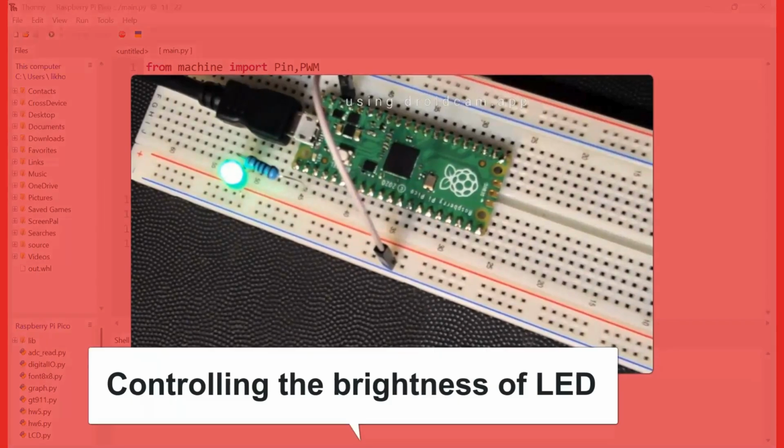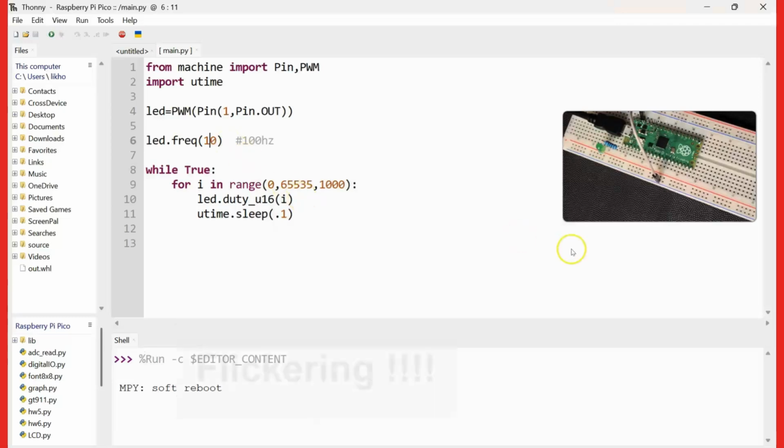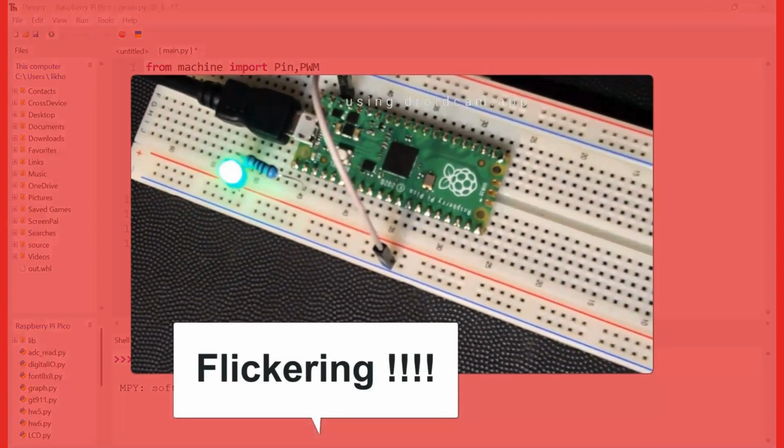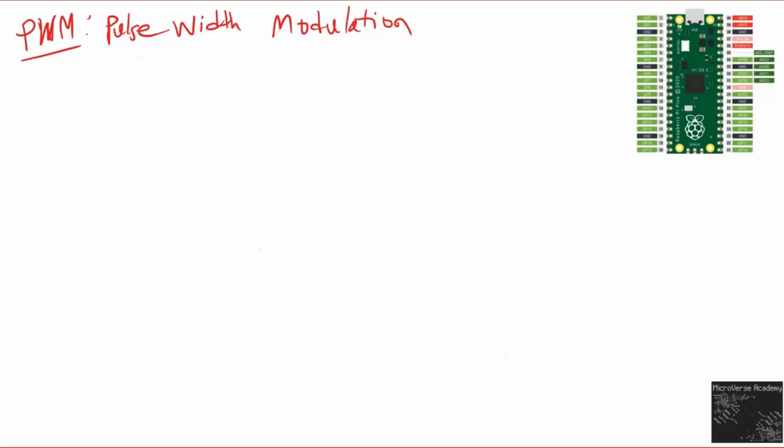The brightness is increasing too fast, and then it goes to 0 and goes to 100% brightness. So here you go. You see, if I make it only 10 Hz, that is too low a frequency, then we see some flickering effect.